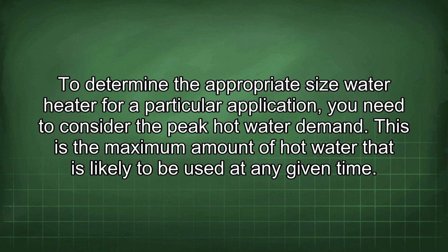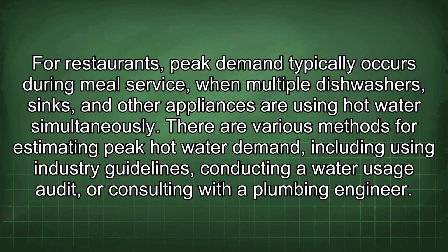To determine the appropriate size water heater for a particular application, you need to consider the peak hot water demand. This is the maximum amount of hot water that is likely to be used at any given time. For restaurants, peak demand typically occurs during meal service, when multiple dishwashers, sinks, and other appliances are using hot water simultaneously. There are various methods for estimating peak hot water demand, including using industry guidelines, conducting a water usage audit, or consulting with a plumbing engineer.